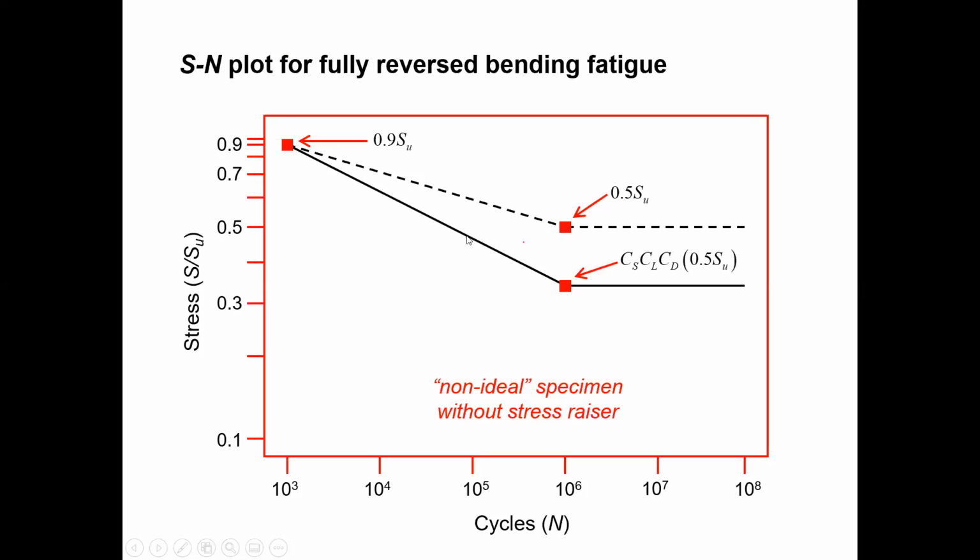But if it breaks somewhere before, it will not reach the endurance limit. That's the meaning of that. So this is not the shear stress. The shear stress is included here, if it is torsional load, we address that with the load factor.